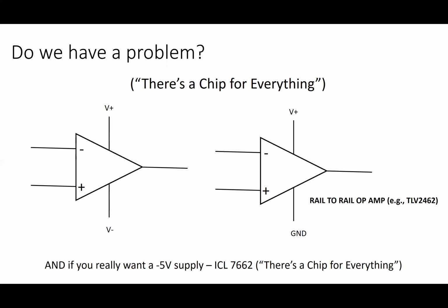However, the first problem you're going to encounter when you go searching the web for operational amplifiers is you will see connections to a plus and a minus voltage source. What's all that about? Well, usually one wants to operate this op-amp around 0 volts. So for example, with this pin connected to 0 volts and then feedback applied across here, the inverting input would have to send this output down below 0 volts. And so you need a supply that is negative with respect to 0 volts. And so almost all op-amps require a dual power supply like this, and that's very complicated.